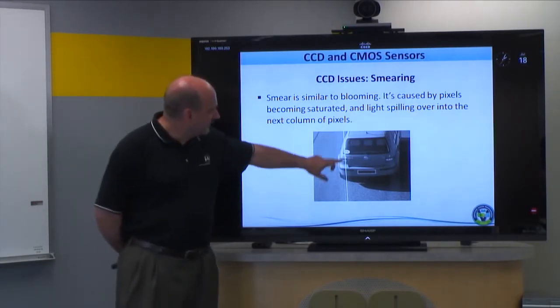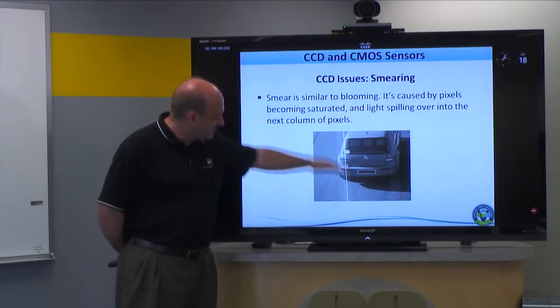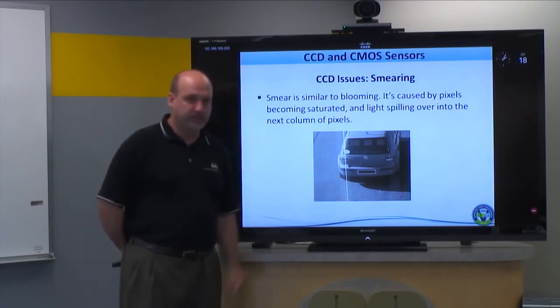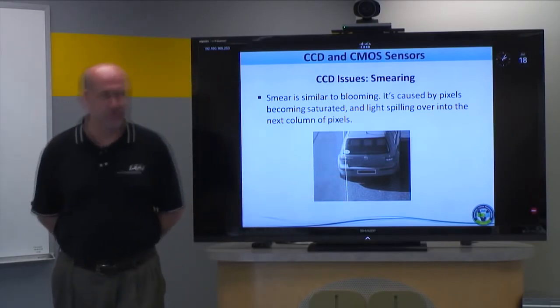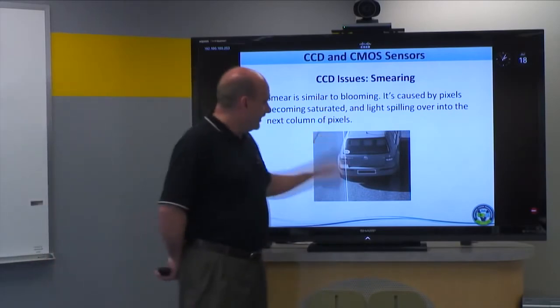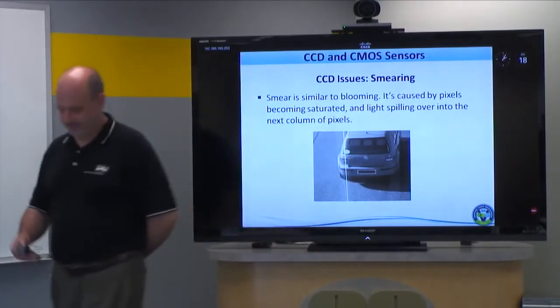So even though this is the hot pixel off the glass here, these other pixels didn't have this charge, but when it rolled, because the whole image is being shifted vertically down the face, it rolled into shift registers that were used by other pixels and continued to streak in there, and this is why you get a vertical shift streak. And you'll notice even on the bright side of this car, there's a little bit of smearing going on here as well from the daylight.